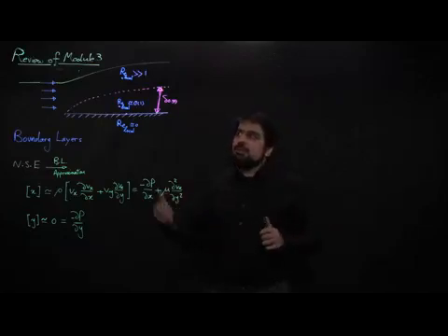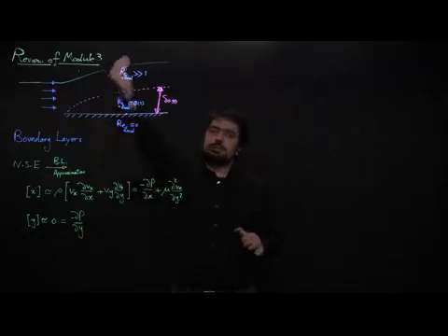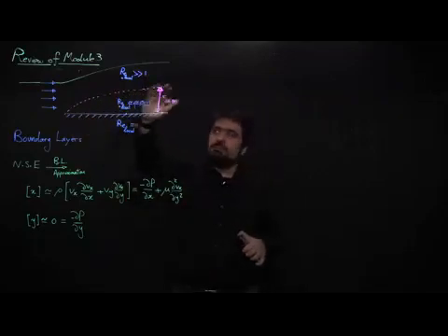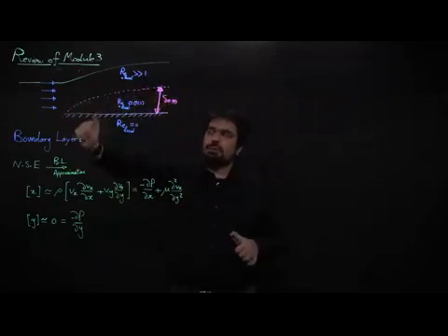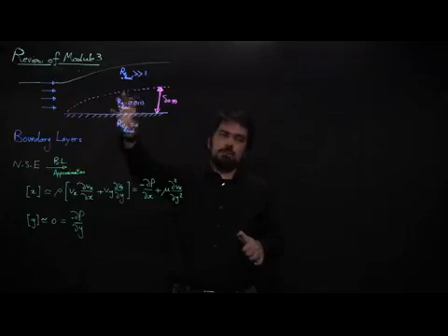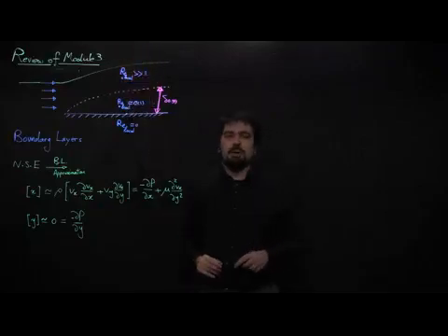So there is clearly a transition from a region where Reynolds number is 0 to a region where it is much larger than 1. Maybe we can separate the flow with the idea of a boundary layer into 2 regions: a region within which the local Reynolds number is of order 1, going to 0, and a region outside it where the local Reynolds number is definitely much larger than order 1.